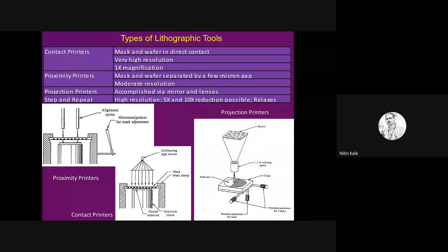So just to have a quick recap, we were discussing lithography, where we said it's a definition step, and we wanted to transfer a certain pattern onto the photoresist. These are some of the tools that are used for doing lithography. Basically, you have the optics, and then you have the alignment, a UV source, and some sort of